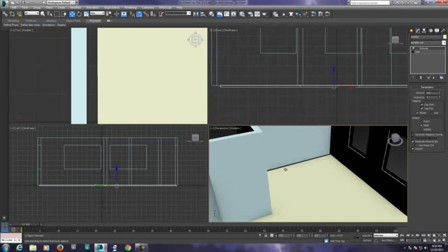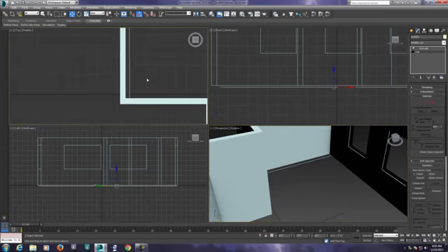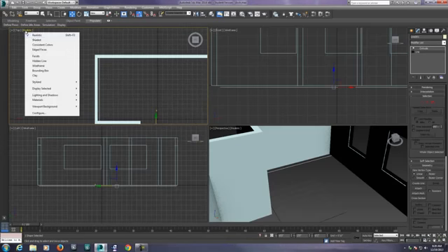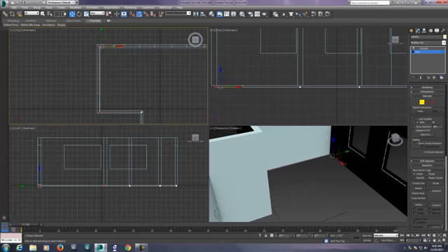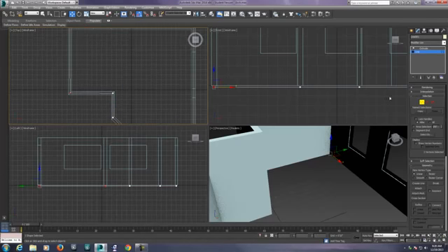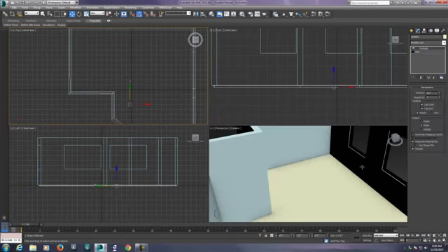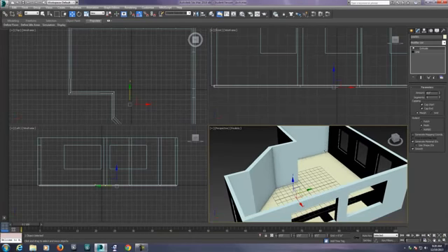And that's a common mistake that I see in architectural walkthroughs, is people have these gaps along the walls, and that is very distracting when you're walking through and you see big gaps and you see the sky or whatnot outside. So remember, if you do that, fix that problem by going in and actually checking to make sure that all of the vertices lie outside of the interior wall. And now when I go back and do an extrude, there we go, there's my floor.